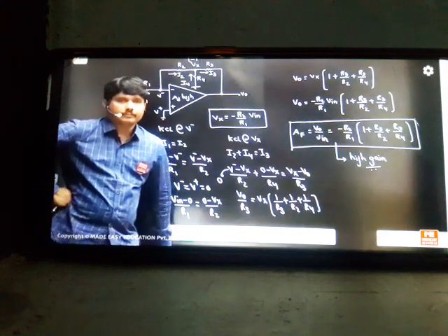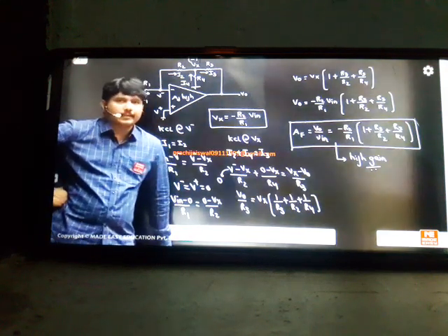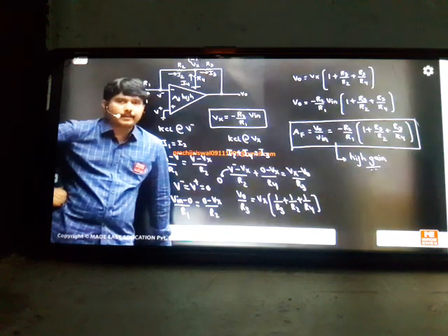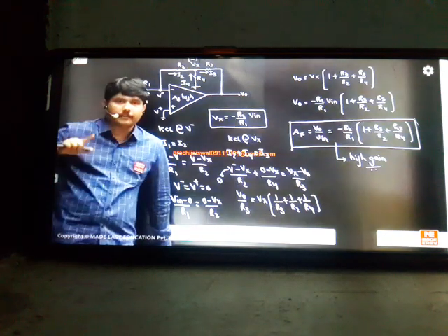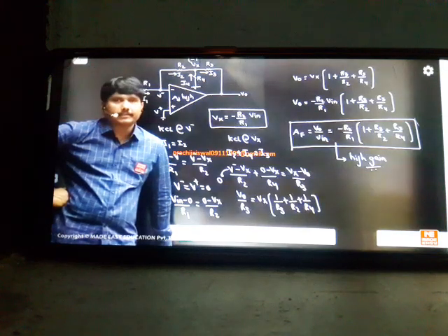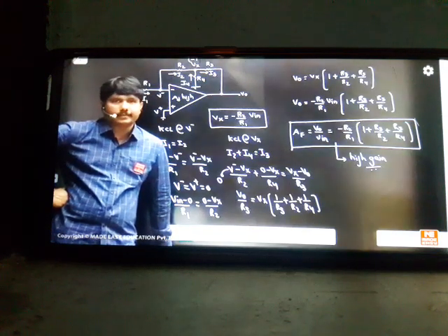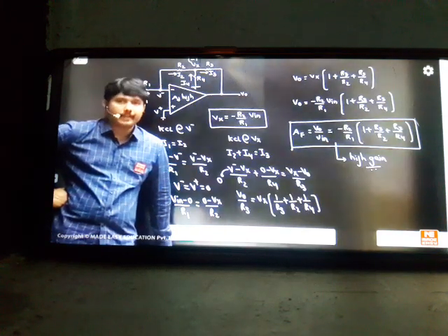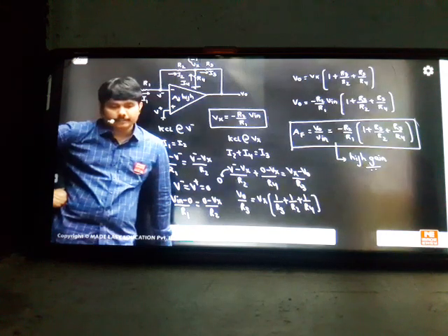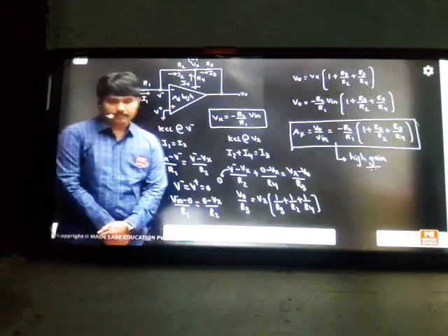Samlesh, here one thing you understand: in this design, space is one concern, that is, space inside op amps. Outside op amps, any number of resistors you take is no problem, for instrumentation amplifiers, because in instrumentation size is not a matter. But the problem here is that we cannot take mega ohm resistances in the designs. We have the choice of taking kilo ohms in electronics. Mega ohm resistors we cannot take in my designs. That is the main reason we have 1 to kilo ohm designs here. Mega ohms are not preferred in the designs.